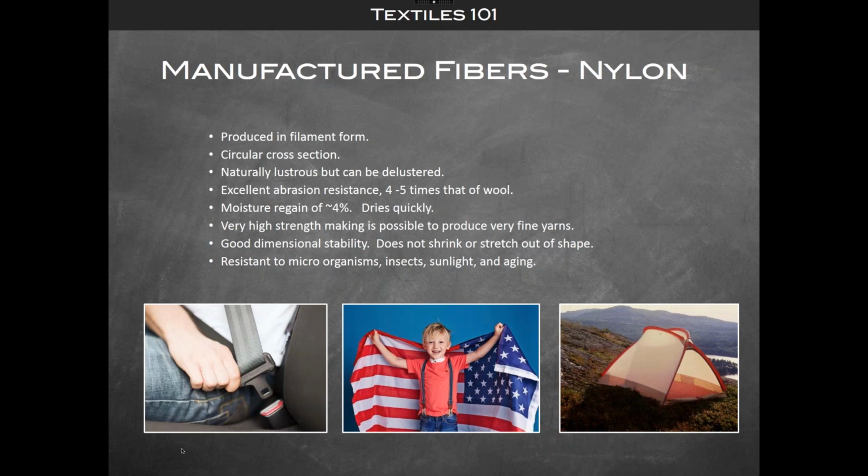It dries very quickly. And nylon also has very high strength, which makes it possible to produce very fine yarns. Nylon has good dimensional stability. It does not shrink or stretch out of shape. And it has good resistance to microorganisms, insects, sunlight, and aging.